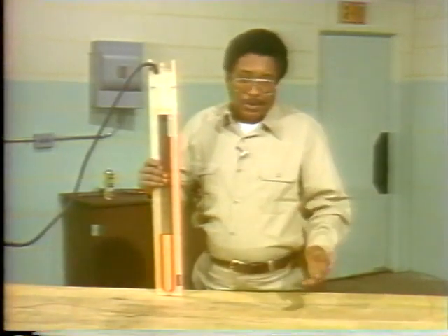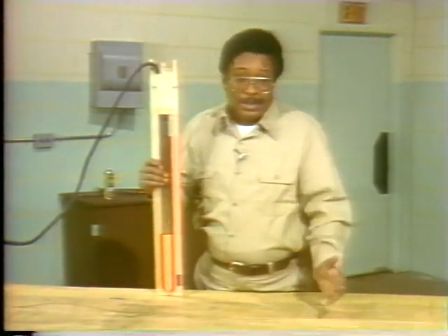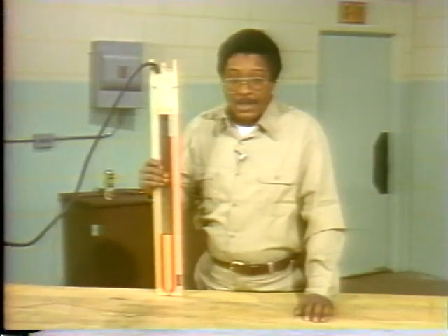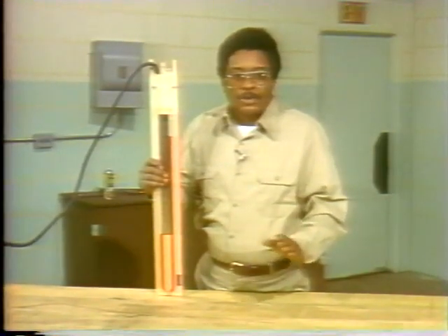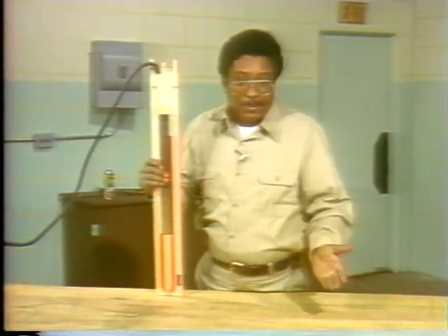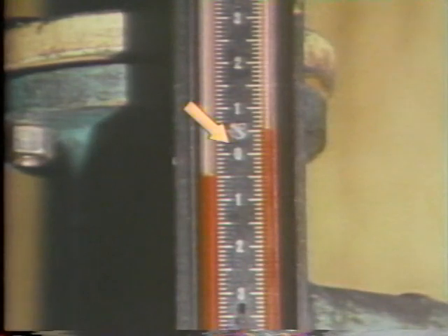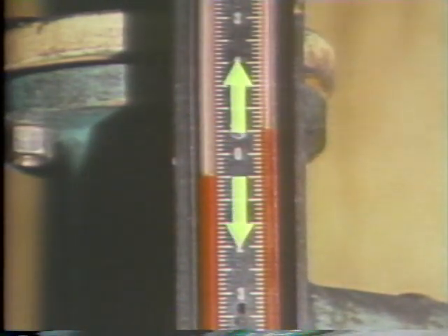Now, it won't be necessary for you to carry a ruler around with you to take readings from manometers in the plant, because there is usually a scale marked off on or near the column of liquid. In this example of a manometer connected to a main lube oil tank, 0 is marked on the scale at the point where both ends of the water column will be when the manometer is under an equal pressure. The scale progresses both above and below 0 and is measured in inches.